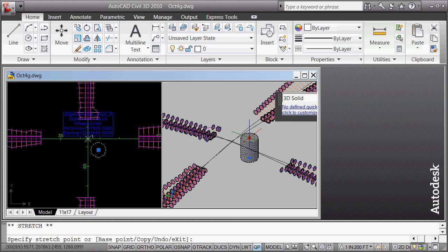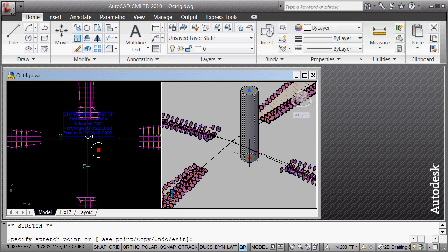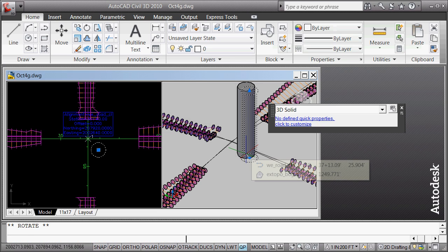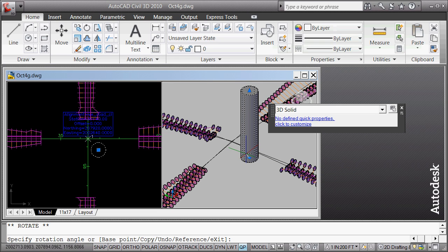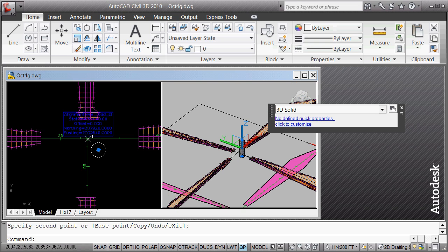you've got some real potential there in the grip editing. One of the more interesting things is that it changes that coordinate, more or less, that it's not actually the coordinate system, but it is changing that, kind of showing you where you're grabbing. So I've left clicked, so I've grip snapped, I've left clicked again. Now I can spacebar, rotate. Now these are 2D commands, unfortunately, when you get to this point. Scale, mirror, and maybe we're going to mirror about that point. And who knows what it did. Alright, so that's the grip edit.